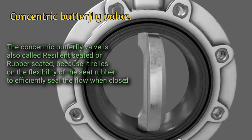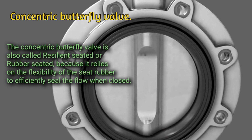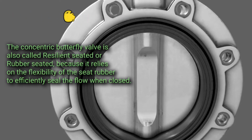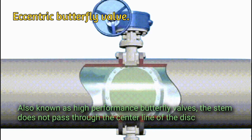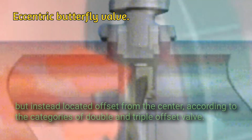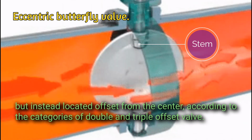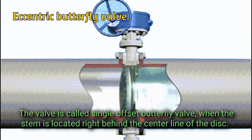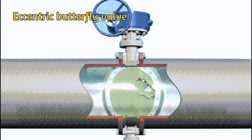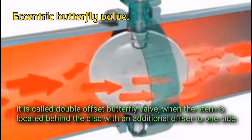The concentric butterfly valve is also called resilient seated or rubber seated, because it relies on the flexibility of the seat rubber to efficiently seal the flow when closed. Eccentric butterfly valve, also known as high-performance butterfly valves, the stem does not pass through the center line of the disc, but instead is located offset from the center, according to the categories of double and triple offset valves. The valve is called single offset butterfly valve when the stem is located right behind the center line of the disc. It is called double offset butterfly valve when the stem is located behind the disc with an additional offset to one side.